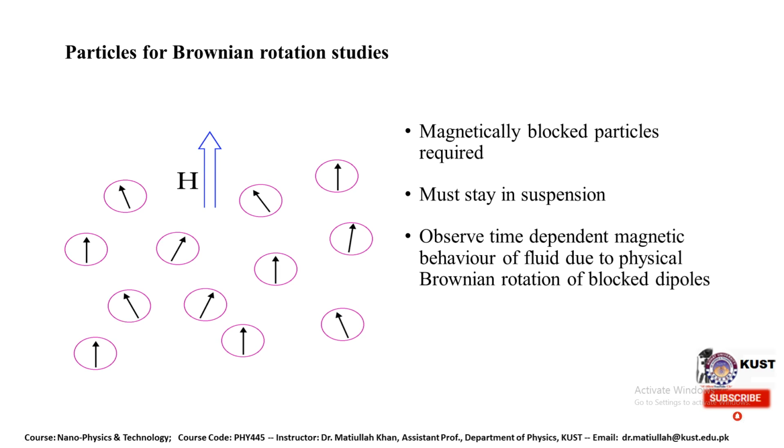It depends upon the strength of the magnetic field, and that is why we have the hysteresis loop, because when all magnetic moments perfectly align in the direction of the field, we have saturation magnetization. If we increase the strength of the magnetic field, the force acting on the magnetic dipoles to align them in the direction of the field will increase, because more energy is required, so the magnetization will increase.